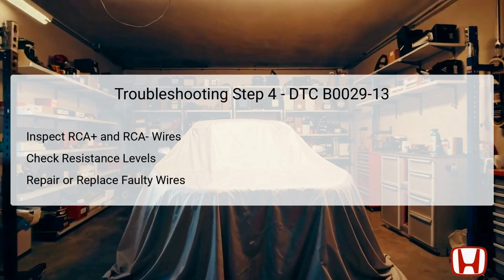Higher resistance can indicate a break or fault in the wiring. If any abnormality is found, repair the damaged wires or connectors as necessary to restore proper connectivity for the SRS. This helps eliminate potential circuit faults that could trigger the DTC.